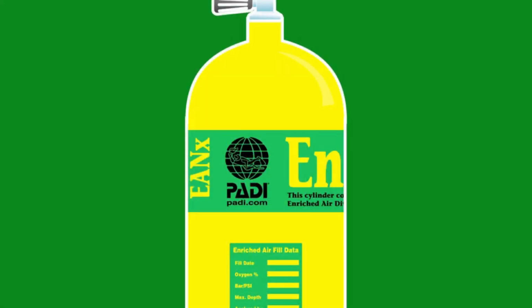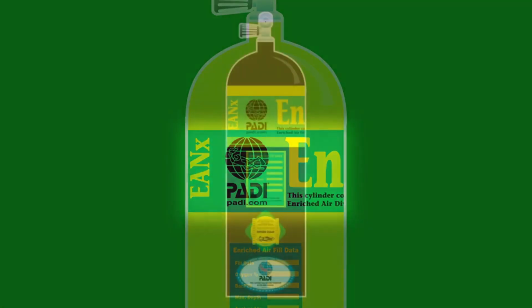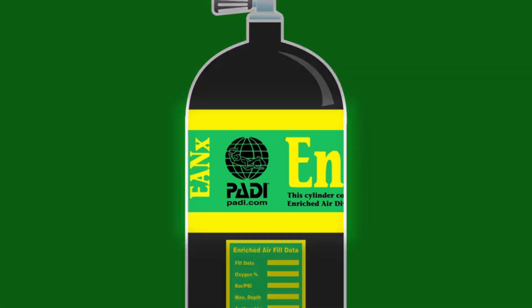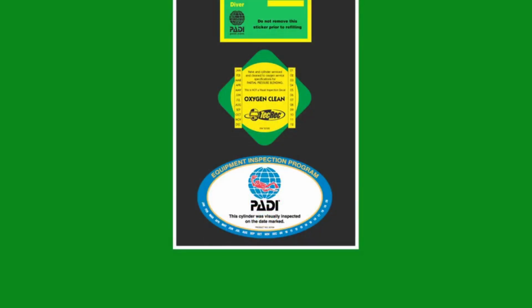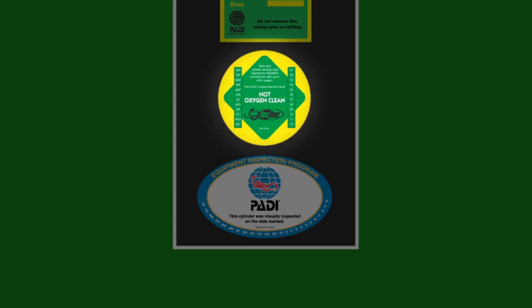Yellow cylinders have a 10 cm (4-inch) green band with yellow or white lettering reading enriched air nitrox, nitrox, or something similar. Non-yellow cylinders should have a 15 cm (6-inch) band with the top and bottom a yellow 2.5 cm (1-inch) band and the center 10 cm (4 inches) in green. There should be a dated visual inspection sticker like on an air cylinder and another stating whether it does or does not meet oxygen service standards.